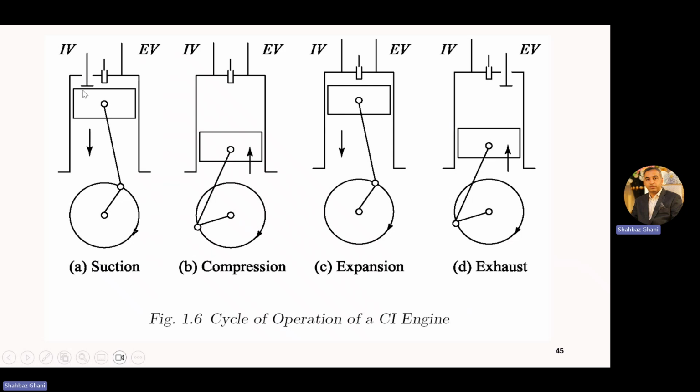Intake valve open, piston is moving from TDC to BDC, suction is there. Intake valve close, piston moving from BDC to TDC. When it reaches TDC, before TDC, you get the injection of the fuel. Ignition starts due to high temperature, high pressure of the air.